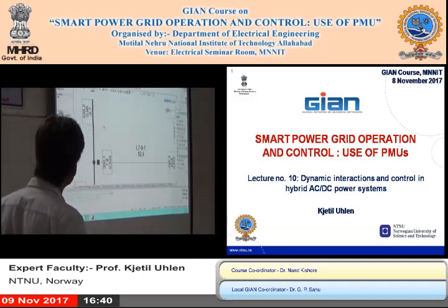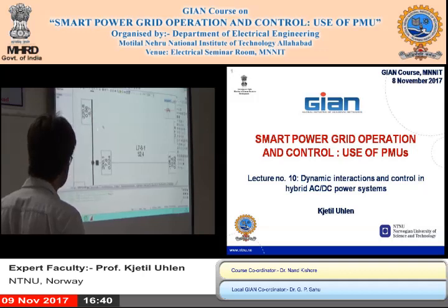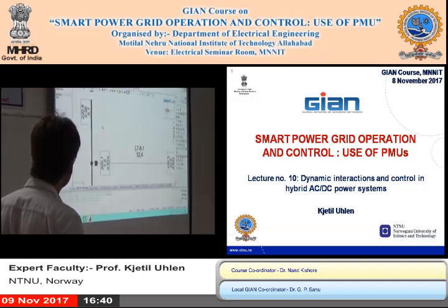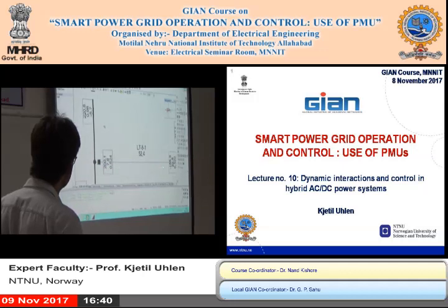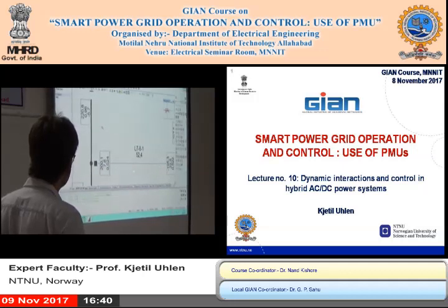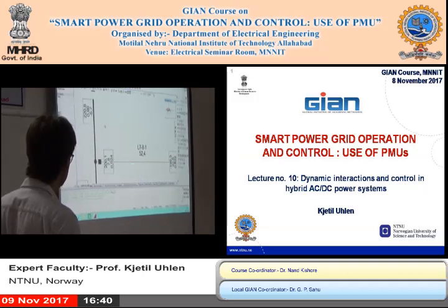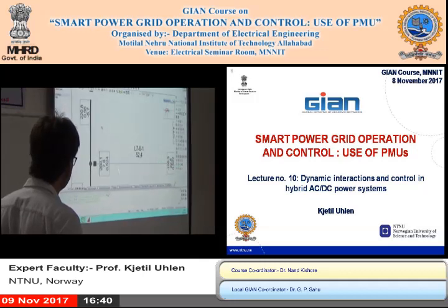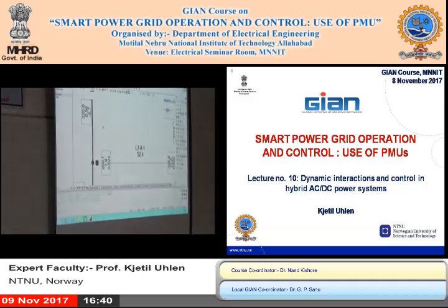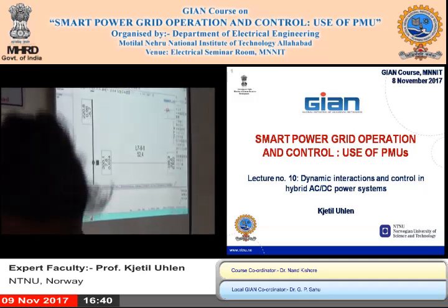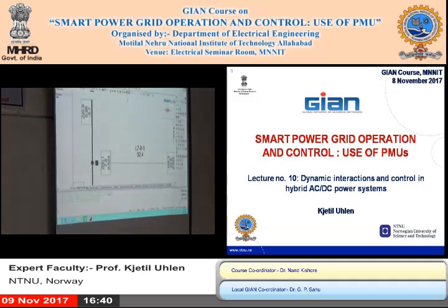So 221 kV here, angle minus 5.7 with respect to a reference. 200 megawatt is flowing in this line, and 7.8 megavars reactive power. And you see almost the same here. That's a certain amount of losses. And there is a supply of reactive power from both sides. That's the power flow. Let's run the simulation.